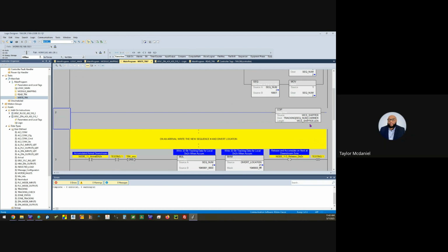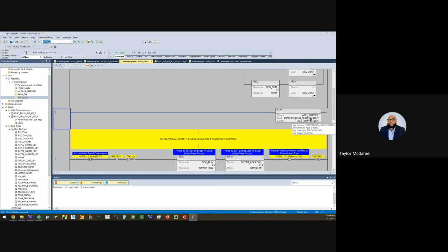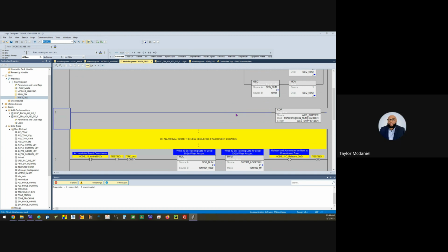Tracking word 1, 0, 1 if the sequence is indirect. Yeah. So right now we're at sequence 2. So this information would go into sequence number 2 at the carrier. So that's how all this works together, how to use a sequence number to fulfill our requirement of numbers only, where something has to change, and then applying it towards a real-world Allen Bradley project, with tags with real meaning, real information. Gotcha.